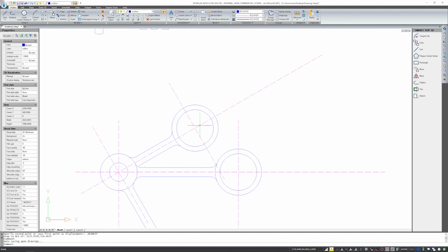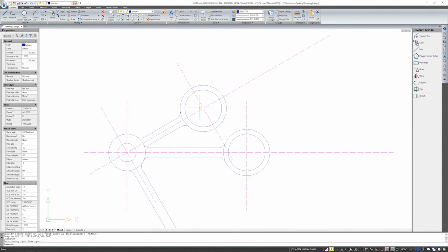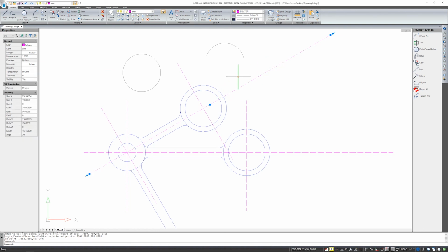I still have a fairly important clone option, but maybe I will do it in such a way that I will now move to layer 0. And here I'll introduce a circle, some arc. You can see that I'm on a different layer than the axis or my circle. And now I would like to copy all this information about the layer and settings of a given line. I do not copy an element because when I copy an element, it includes its length. I want to clone it because I want to enter the same element but with a different angle and length.